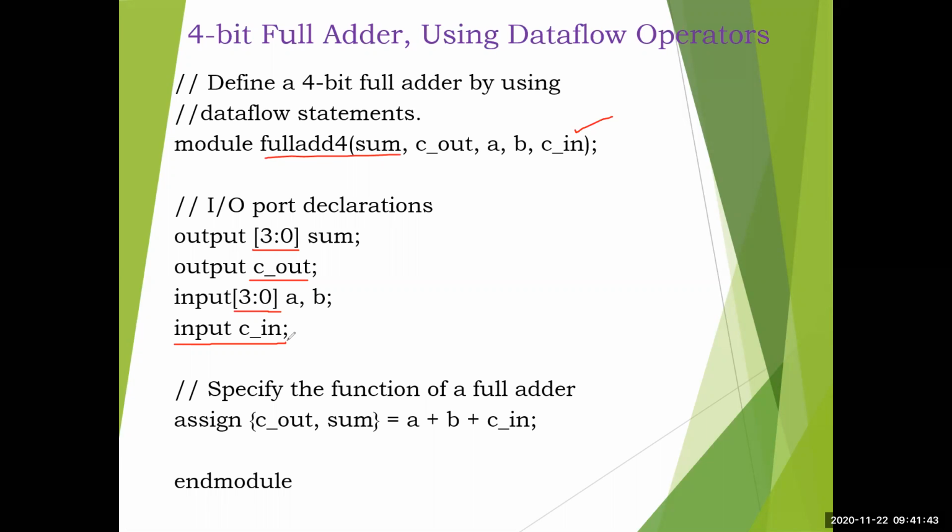Earlier, in the circuits we have done, we wrote the Boolean expression, simplified it, drew the gate level diagrams, and then called the gates, right? We used 2 XOR gates, 2 AND gates, and 1 OR gate. In the exercises you have also seen a 1-bit full adder with basic gates. Now, in dataflow modeling, just operators are there in your hand.